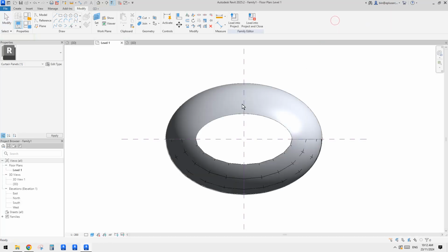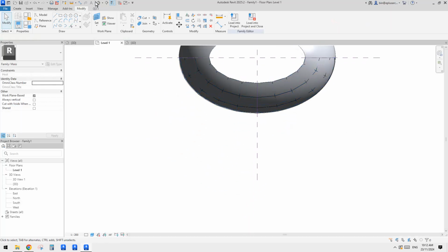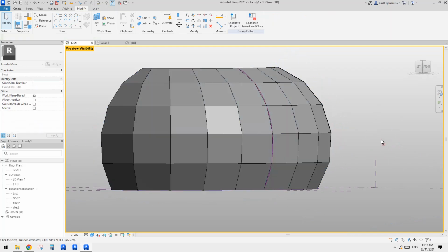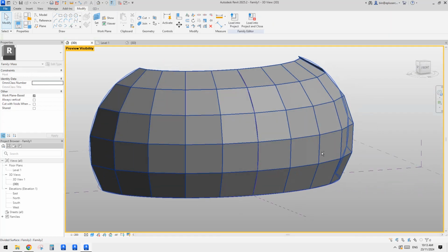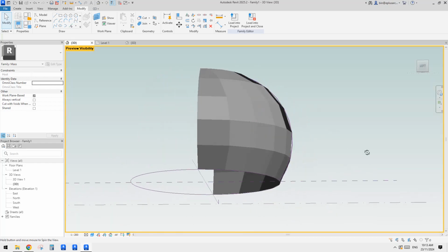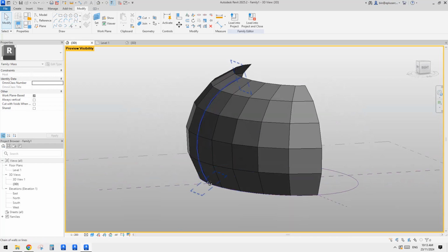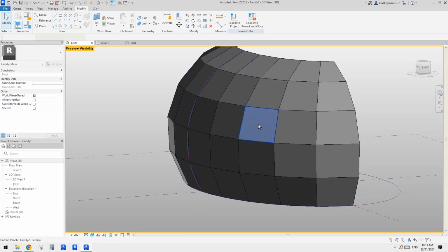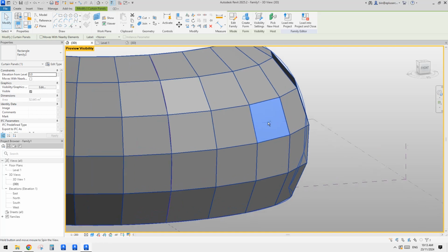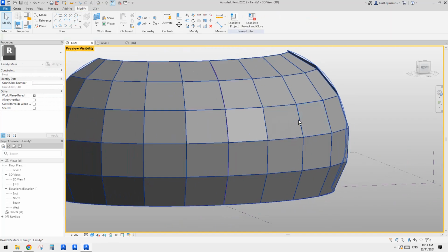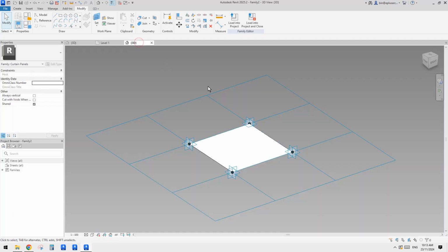And now if I load this one into here, and then let's go to 3D view again, select this, and then apply that family to it, you will see it's flat. Now you can see actually it looks better. I mean, you can tell it's all quite flat, right? So now we try to adjust this pattern-based family so it creates a curved surface instead of this type of flat surface. Okay, so let's start.